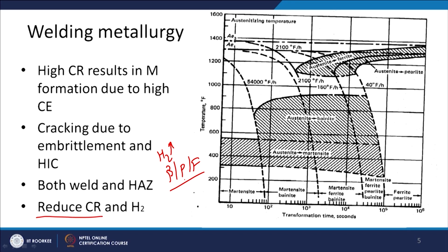There is one more aspect, which is related to the preheating of the steel. We know that in this case the formation of the martensite will start on rapid cooling at 550 degree Fahrenheit. So if we give any preheating to the steel, the formation of the martensite during the welding can be avoided. Normally a 600 degree Fahrenheit preheat is preferred, but working with a higher degree of preheat is difficult, primarily due to working with hot plates as well as the oxidation tendency of the steel.